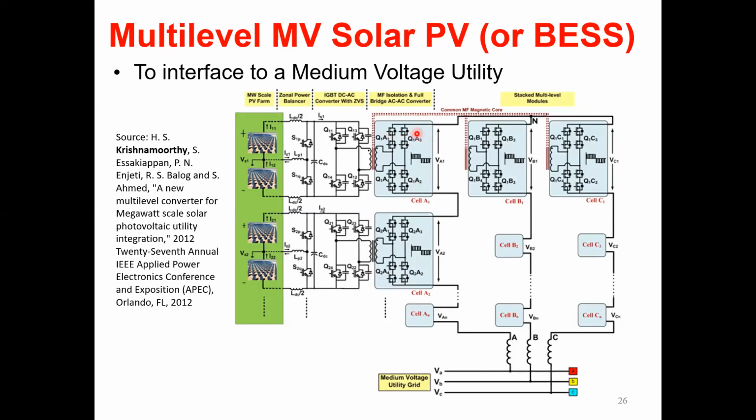So this solid state transformer is operating at medium frequency, I think about 600 hertz or something. So the size of the transformer could be significantly reduced, because this is a very large power application. And then for high voltage, what do we do, right? Because there is one aspect of high frequency transformers: you don't want the corona losses to be high.